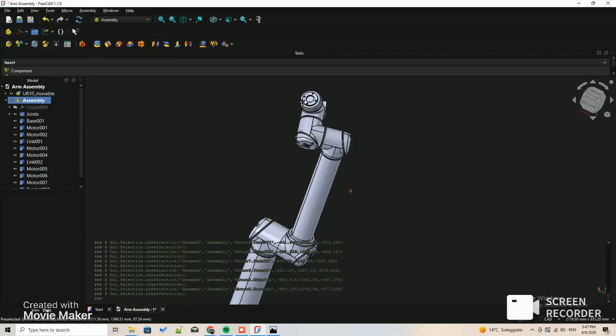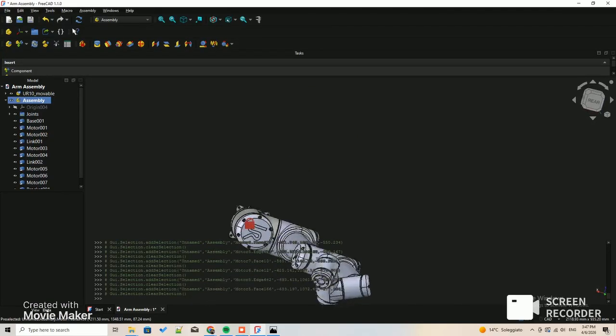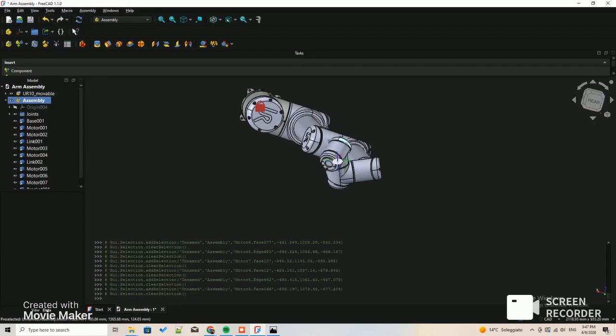This one is correct, both from the look point of view. So we have the motors back here, which is supposed to rotate this bracket and end effector. Okay, so this part should be stationary and would be rotated with this motor. So each motor could only have one rotating axis, one rotor. So if this is the rotor, this part should be stationary, which itself is rotated by this motor.